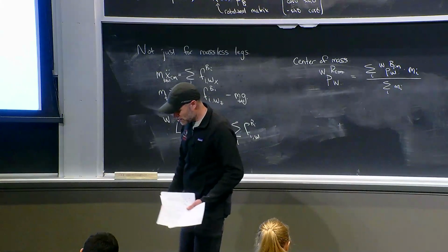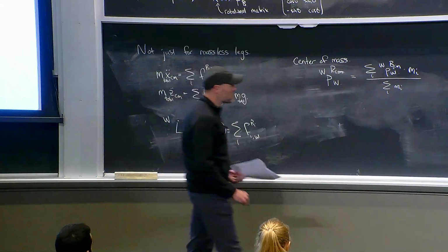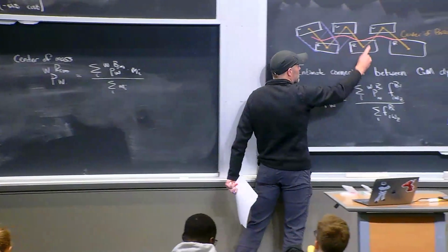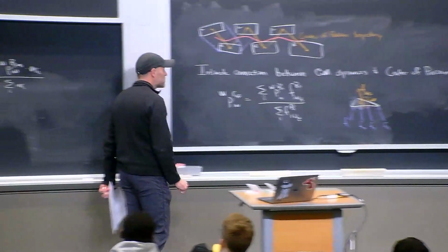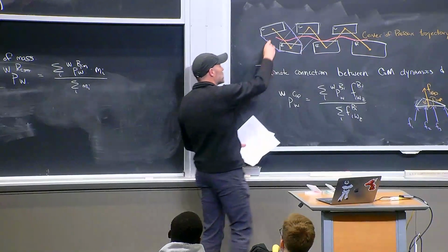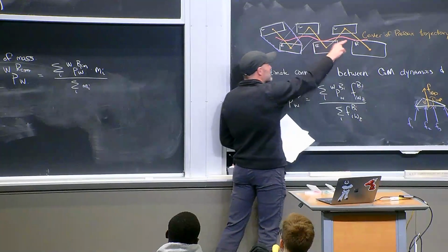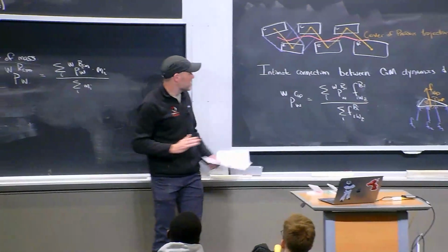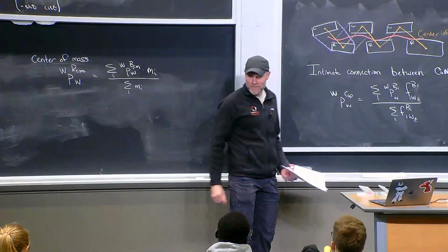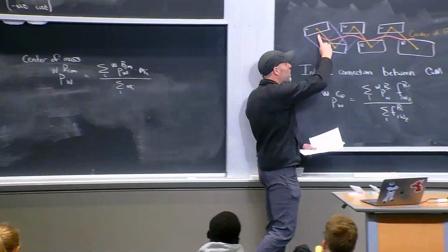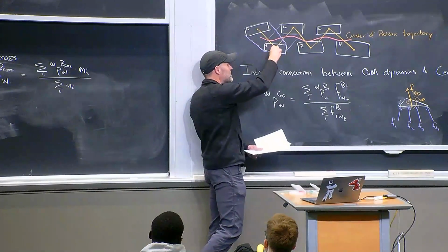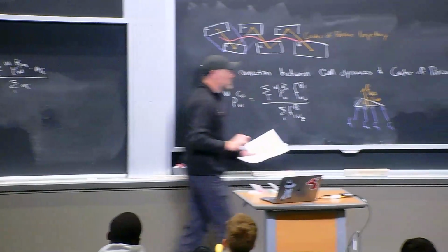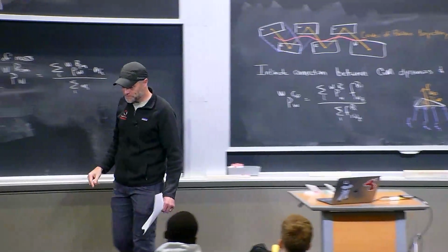Okay. But if the timing on your ZMP trajectory, your center of pressure trajectory, is faster, then actually you can achieve this with a center of mass that never even goes over your feet. Okay, and you get a dynamic gait. Right? You get dynamic walking, meaning that you're always falling down effectively, okay? But you can catch yourself and you get these trajectories that are much straighter.